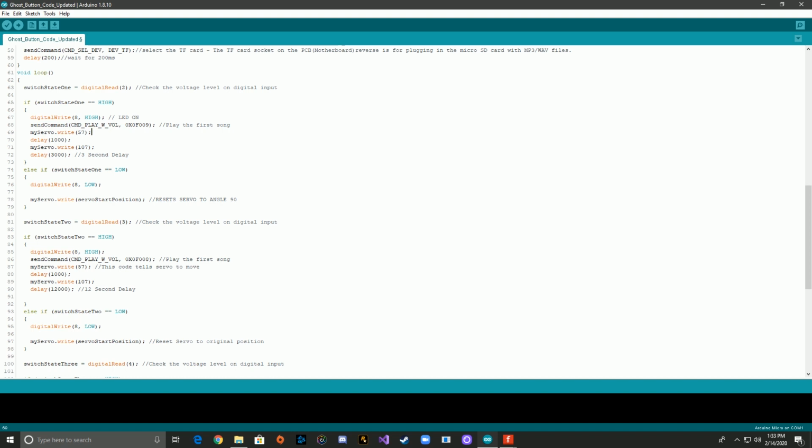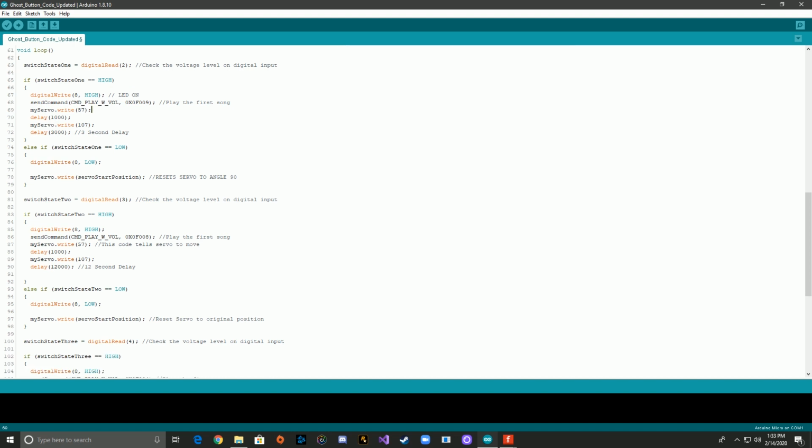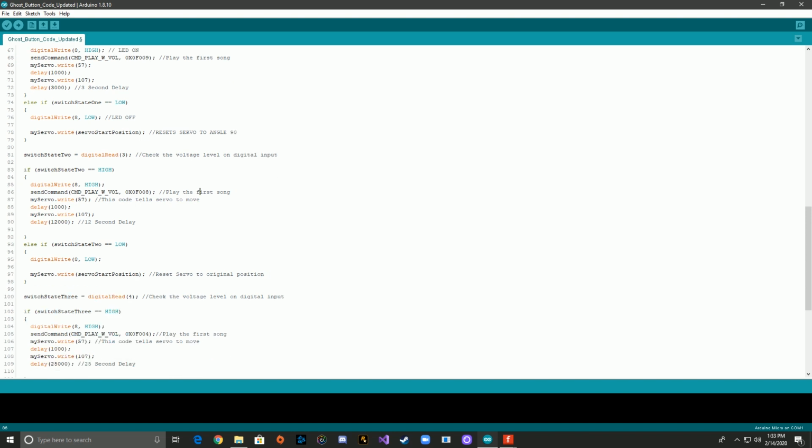Yours is probably different. After that, myservo.write, this is what makes it move. Wait a second, write again. Wait 3 seconds. We wait 3 seconds because that's how long this first MP3 file is. And then if it's not been clicked, we can probably just use else. You don't have to do an else if. You can just do else, switch state 1 is equal to low, digital write 8 low, the LED is off. Right there. myservo.write, set it back to the original start position. Copy and paste. Boom, boom. That's for all three of the buttons.